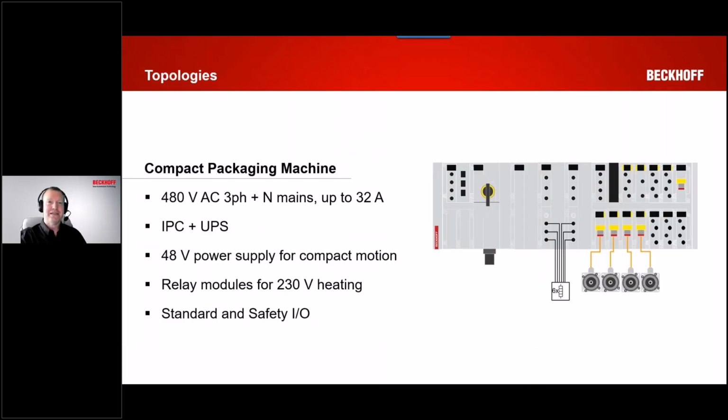So think about the design time and the wiring time that goes into putting together a heating section of a machine, where now we can send say an M12 cable out to a heater and an M12 or M8 connector back to a connection here for feedback, and we're there. The rest becomes plugged in to the setup, providing the power to the disconnect, and programming it. So fairly straightforward and simple when you encapsulate that functional module.